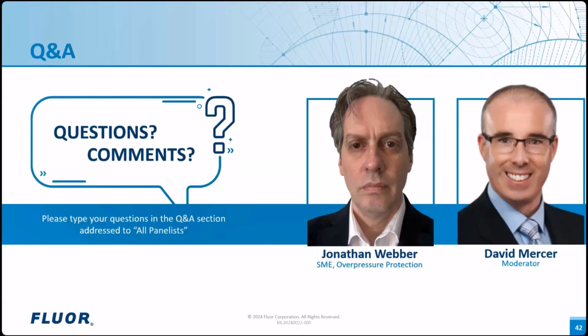But as I said, the use of HIPPS with one P or two Ps is used broadly, and it's not always consistent. There are always other safety functions besides overpressure that can require the consideration of a high integrity protection system. If it's not used to credit the relief load on the PSV or remove the PSV, it's not a regulatory HIPPS, but it's a HIPPS perhaps with one P in its own sense. There are other safety instrumented functions required to reduce risks other than overpressure that can end up being high integrity.